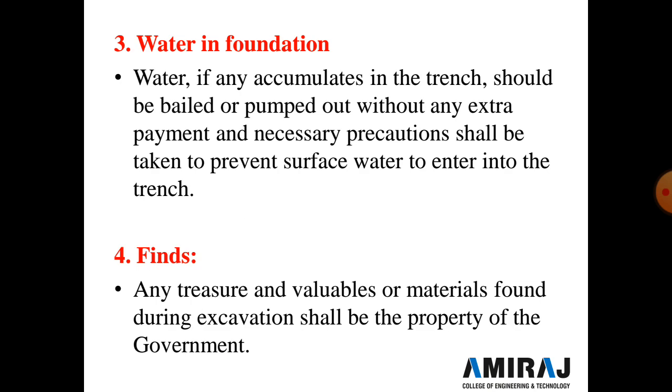Now the third point is water in a foundation. Sometimes if the water table is high, we get water during the excavation time or during the foundation work time. So water, if any accumulated in the trench, should be bailed or pumped out without any extra payment, and necessary precautions shall be taken to prevent surface water from entering the trench.